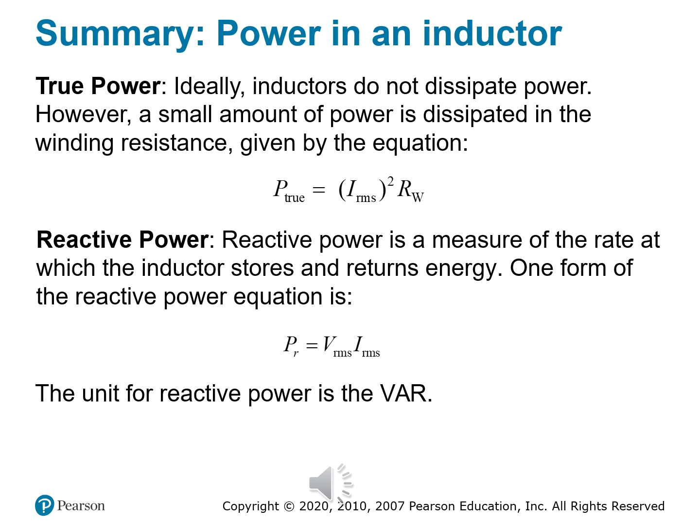Reactive power is not consumed. It's cycled back and forth between the inductor and the source. Reactive power is the rate at which the inductor stores magnetic energy and then returns it to the circuit. The equation for that is P sub R equal to V RMS times I RMS, right? So voltage times current, if you remember the power formula. But remember, this isn't real power like in a heater or a light bulb. It's measured in VAR, or volt-amps reactive, and it's not watts.